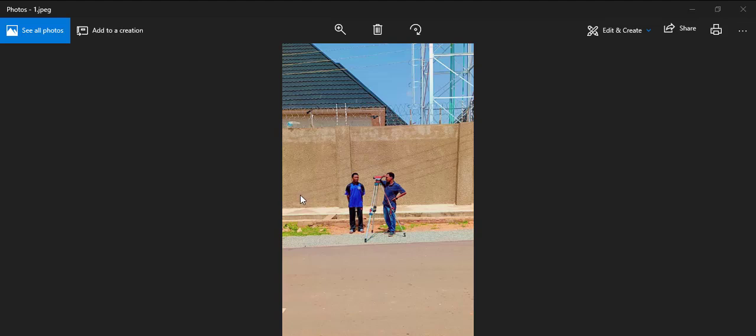If the flood is above the road level, then your DPC should be at least 300 above the maximum flood level. By doing this, your surveyor can tell where your road level is and how you need to go about it.